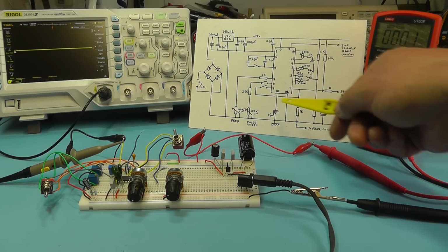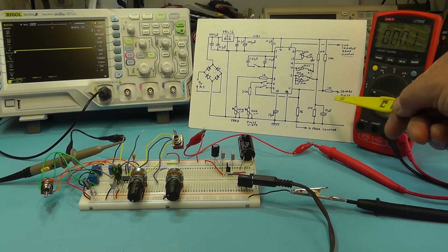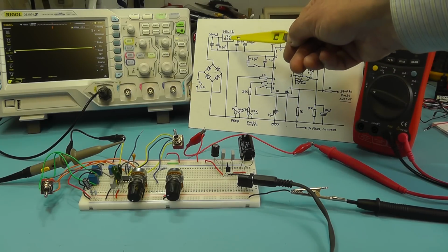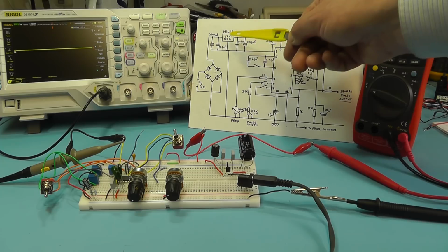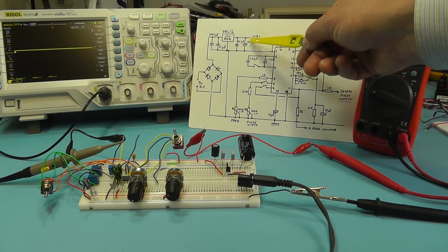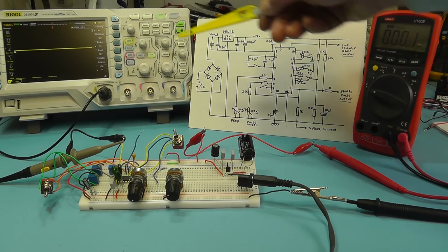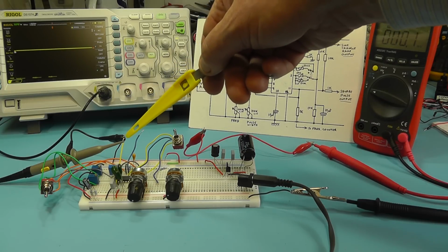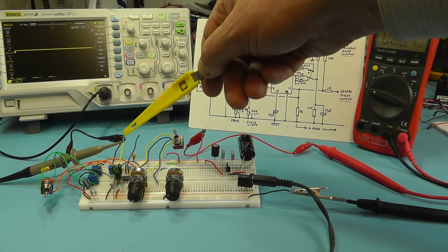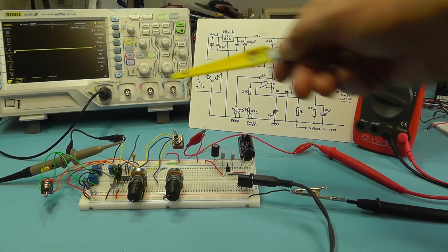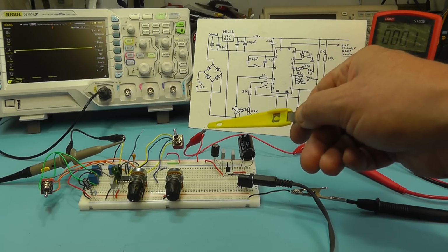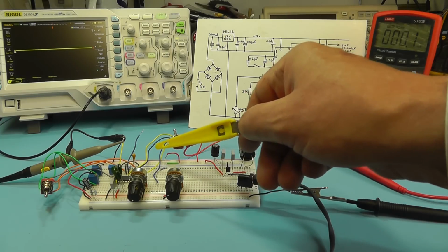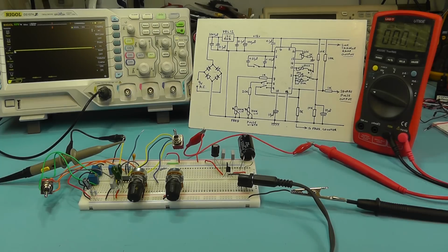At the back there I've got the circuit that we've wired up so far on the breadboard, so that's the function generator IC and the little power supply circuit there with a 12 volt regulator. So we're going to check that 12 volts there first. And I've got the oscilloscope there connected to the sine wave output of the function generator chip. That's going to pin 2 there at the moment. So let me just check the 12 volt supply before I hook up the 12 volts to the rest of the circuit on the board.